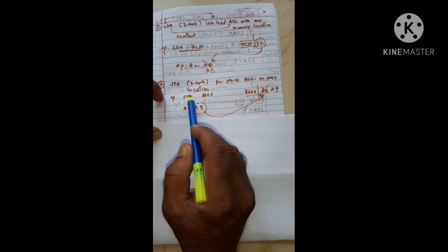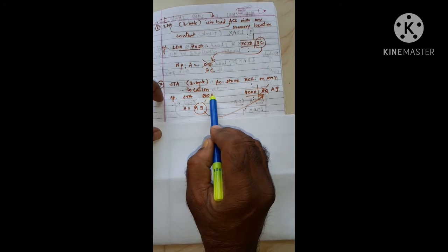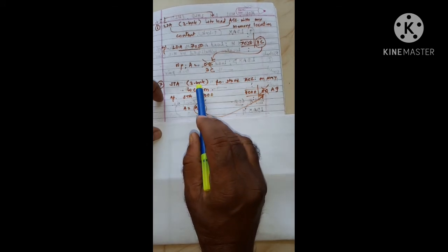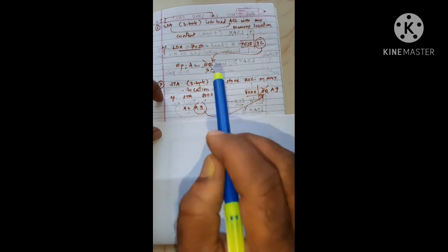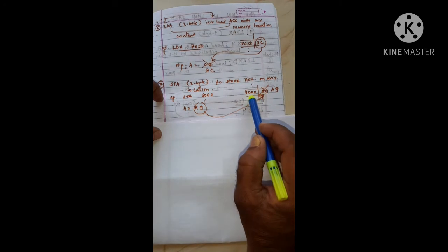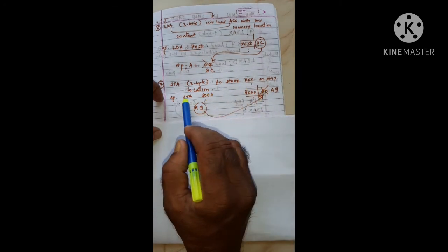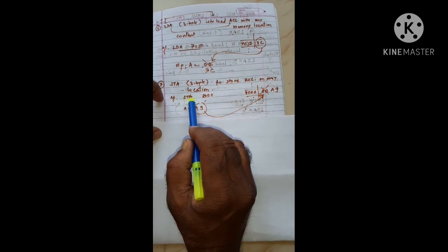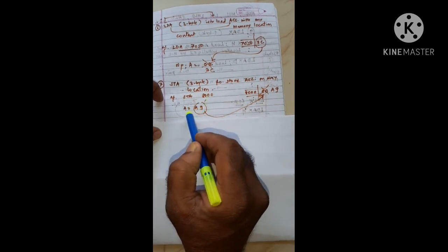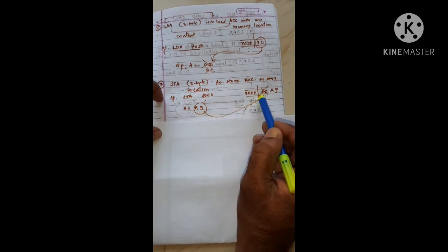Example of how it can be written: STA 8000. The operand 8000 is 2 bytes or 16 bits in binary, that's why it is a 3-byte instruction. If A contains A9 and memory location 8000 contains 00, after the instruction execution STA 8000, the content of A is transferred as it is to location 8000.